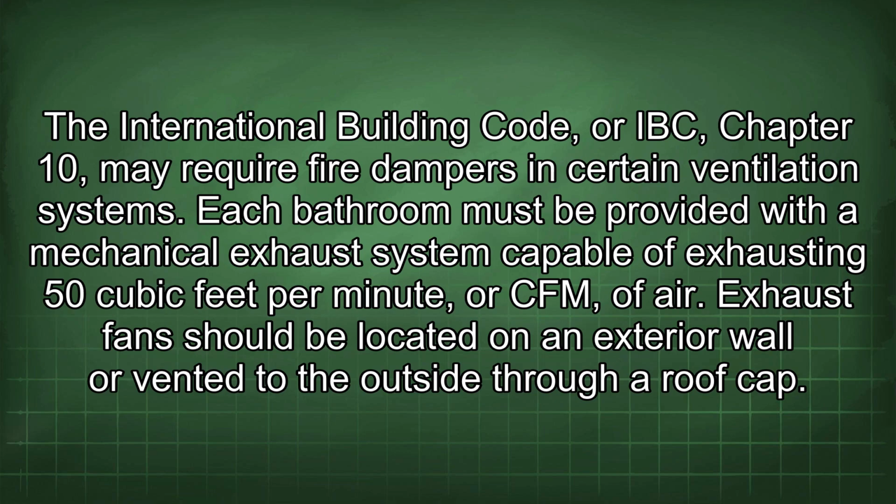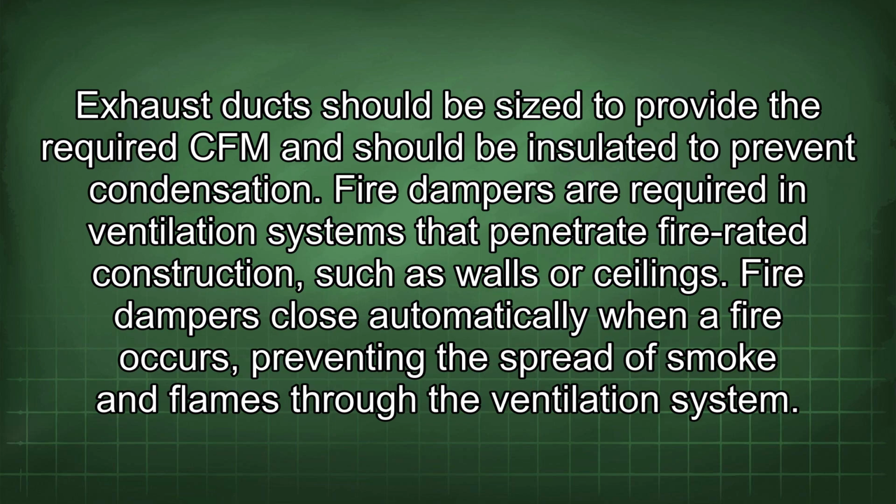Each bathroom must be provided with a mechanical exhaust system capable of exhausting 50 cubic feet per minute, or CFM, of air. Exhaust fans should be located on an exterior wall or vented to the outside through a roof cap. Exhaust ducts should be sized to provide the required CFM and should be insulated to prevent condensation.